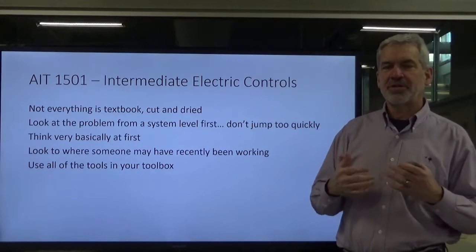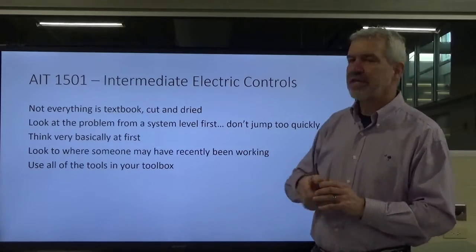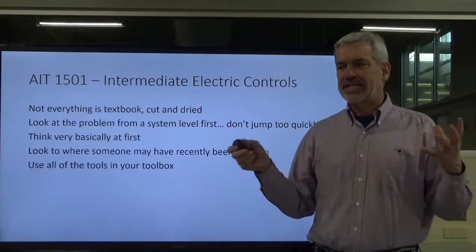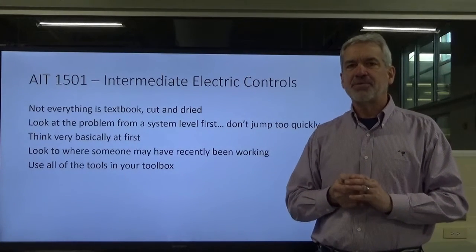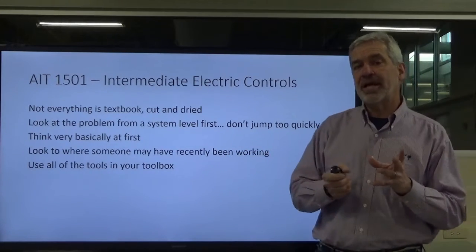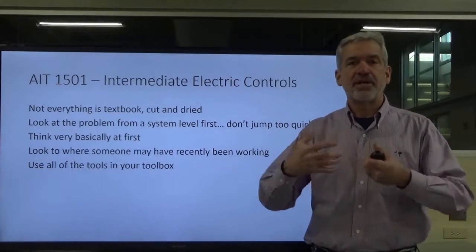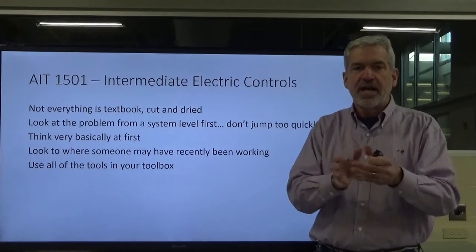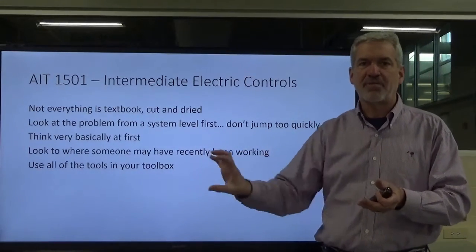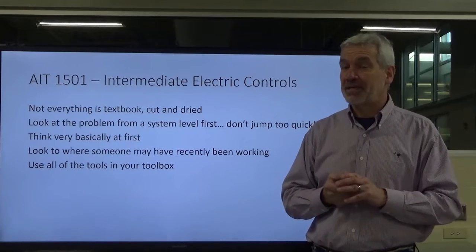So you're going to have to learn, you'll see some more, and you'll think, hey, I remember seeing that at one time. Another thing, look at the problem from a systemic level, from a 10,000 foot view. Let's see what's going on, okay? Maybe it was electrical, maybe it was mechanical. Maybe that contactor wasn't coming in all the way, because in a dirty environment, not theirs obviously, a lot of dirt gets in there, and it won't let that contactor move properly when it becomes energized. It can't travel properly, so you get half a connection. So maybe it's not an electrical problem, maybe it's a mechanical problem.